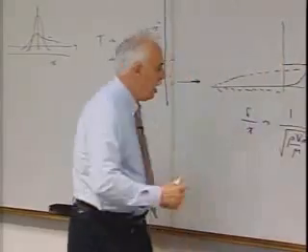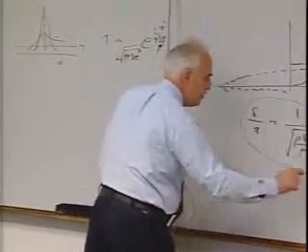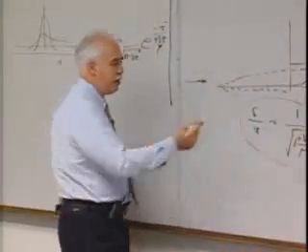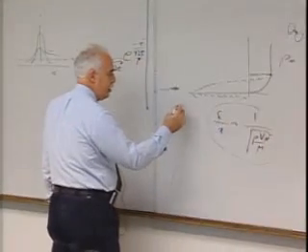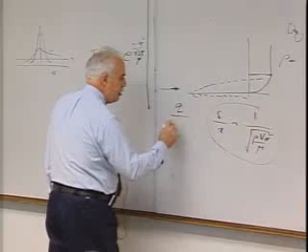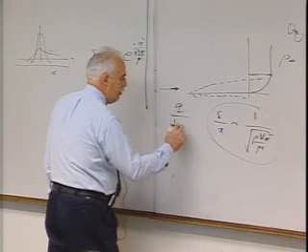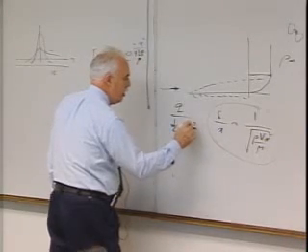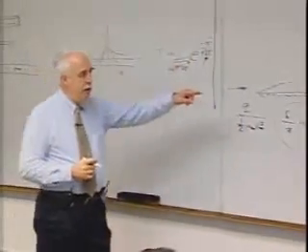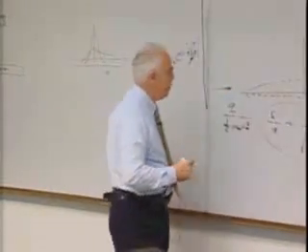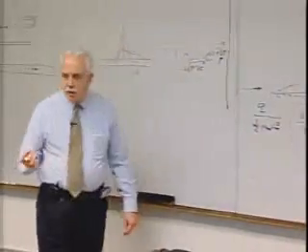Okay. This is extremely important, not just in terms of boundary layer, but also in terms of the Stanton number, which is approximately heat transfer divided by 1/2 rho infinity V infinity cubed for the case of a sphere. Now, this is one-dimensional, obviously, flat plate. A sphere is also one-dimensional.